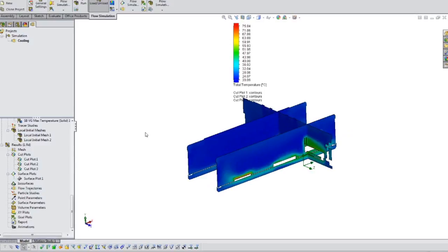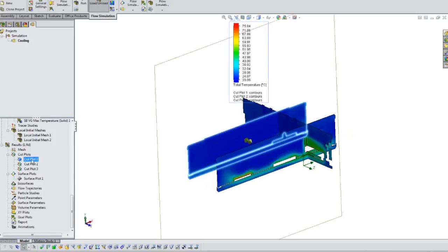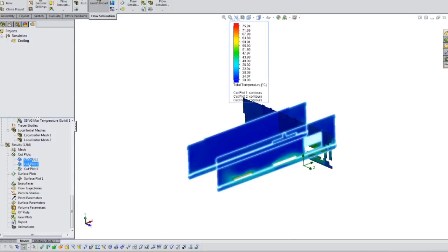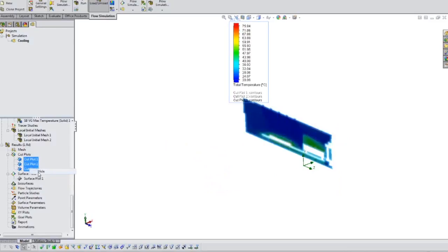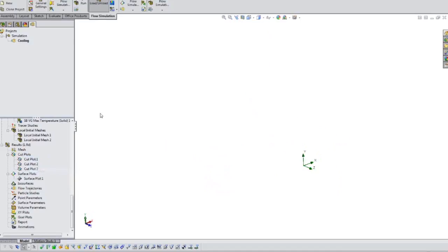And again, like we were talking about earlier, there's only so many thermocouples that you could put inside of a physical model. Inside Flow Simulation, we can use the probe tool to basically put thermocouples anywhere that we want in space, on components, to take a look at specific locations and what those temperatures are. And it's a really quick and easy tool to be able to do that.